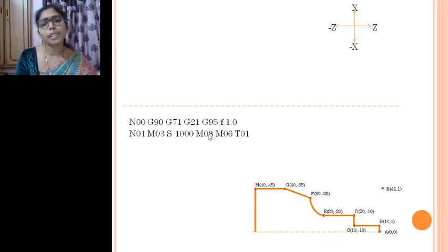And in this also we have different options, whether you need a mist coolant or a flood coolant, the different ways of providing the coolant. So based on that, different codes are present, right? You can select based on the operation which you are performing. And then you have the tool change option, M06. If another tool is placed in the slot, then you have to go for the tool required for this particular operation.